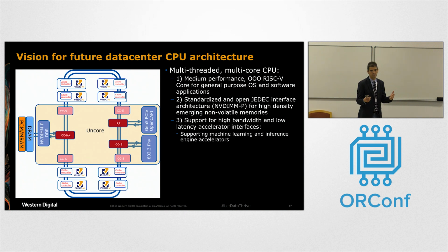Neural networks are most popular, but there are many others, like SVM and K-means. They are all very compute intensive, and they all boil down to fairly complex solvers. Different kinds of accelerators, for both learning and inference, with different performance and power requirements are being developed. They all like to have a high bandwidth, low latency interface to the CPU so they can get and share data. Maybe they want a cache coherent interface so there's no need to do DMA twice. These are very interesting and powerful things that we can explore if we have a fully open architecture.